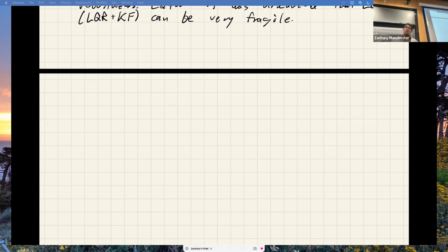You should check the paper out. It's actually very easy to see what's going on there, but it comes down to the fact that you're not really measuring the full state. So you might only, for example, be measuring positions, and then the filter has to infer the velocities using the dynamics model, and then that expected full state gets fed into the controller. So at a deep level, it has to do with that you're also reconstructing the state from partial observations using the dynamics.